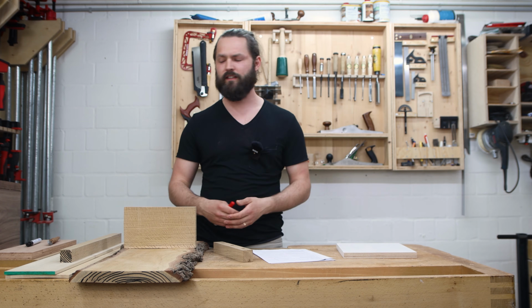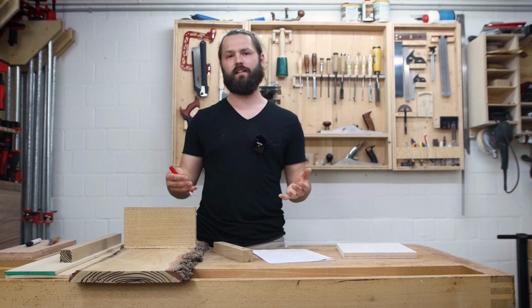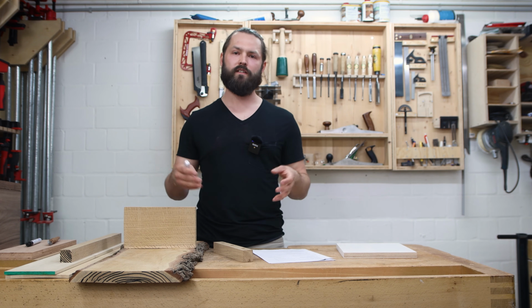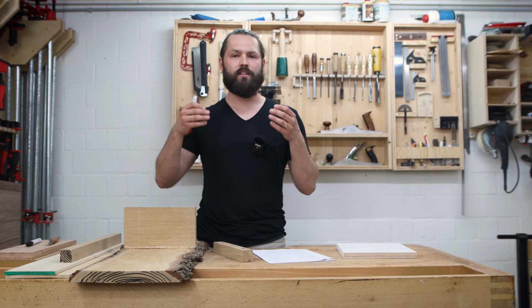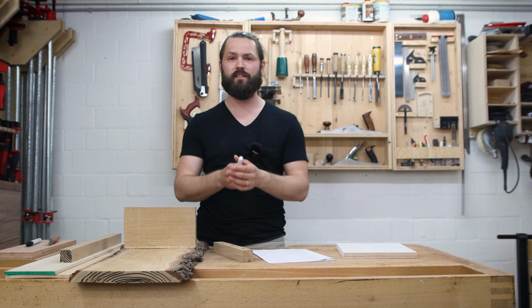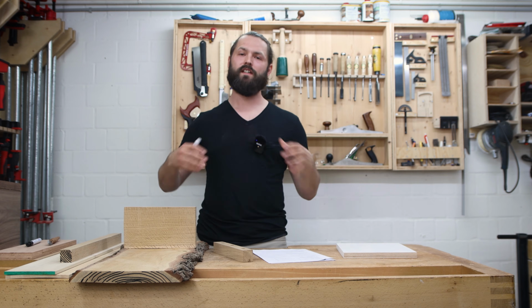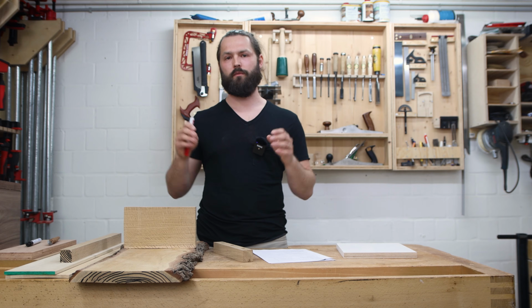Now with all the numbers we've talked about, does it mean for every project we have to get out a calculator, measure the moisture content and really go to town with it? No, it doesn't, but we have to understand this basic concept. That being said, I also advise you check out one of these wood movement calculators online. Just play with it a little bit to get a feel for how much wood actually moves in your project. Is it 1 centimeter? Is it just 5 millimeters? Is it 50 centimeters? Just go there, play a little bit, get a feel for it, and then you can most likely just guess how much it will move.